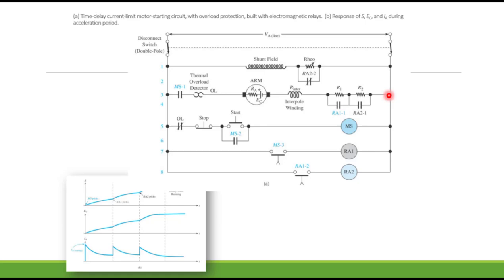We talked about sequencing motors so that you don't have several motors starting at once and have this huge inrush current. Not only can you trip breakers with this inrush current, but it also can produce an awful lot of torque. So you don't want to break shafts or anything else because of the sudden torque that you've created. This starts the current off a little slow.